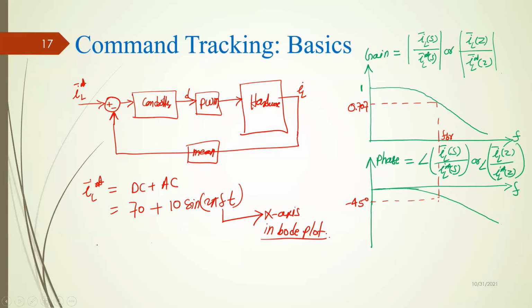And what we do is we make a table. We make one value as frequency. For one operating point I'm discussing, we try to add a 1 Hertz disturbance in the system, and then we sample, and then we do FFT. So you can do FFT of IL average.